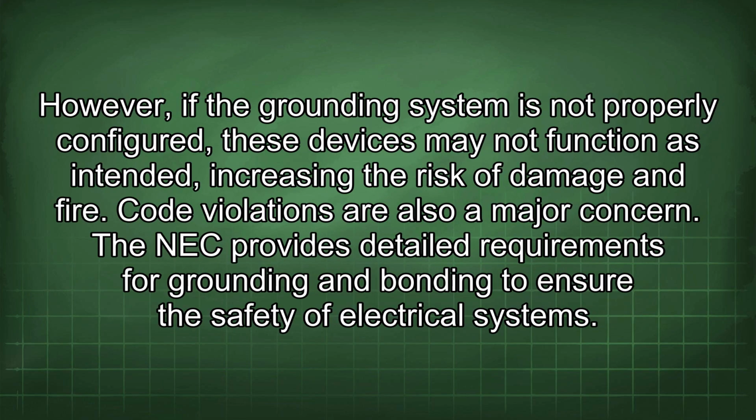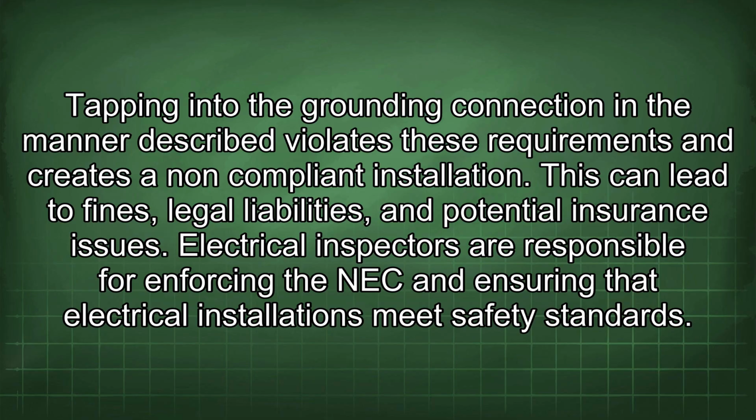However, if the grounding system is not properly configured, these devices may not function as intended, increasing the risk of damage and fire. Code violations are also a major concern. The NEC provides detailed requirements for grounding and bonding to ensure the safety of electrical systems. Tapping into the grounding connection in the manner described violates these requirements and creates a non-compliant installation. This can lead to fines, legal liabilities, and potential insurance issues.